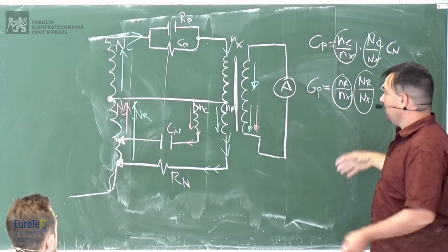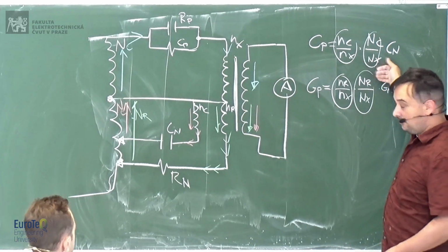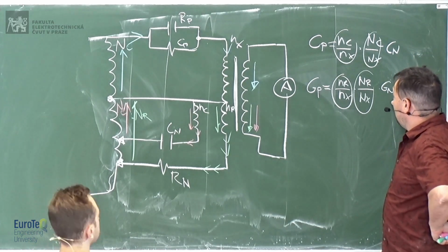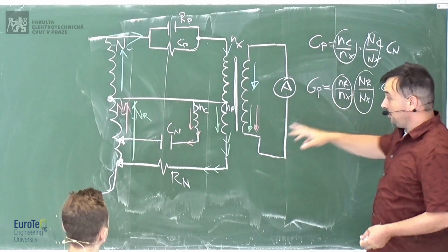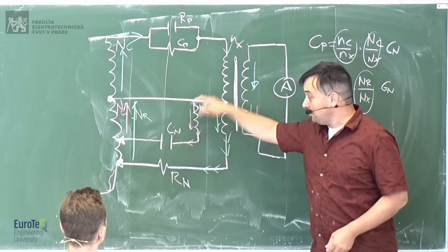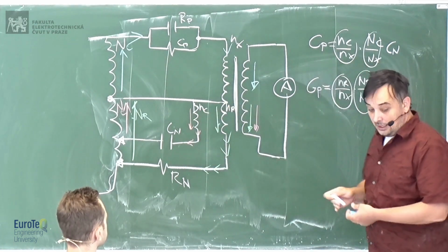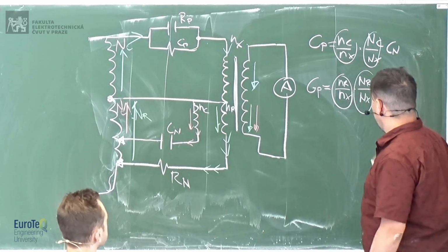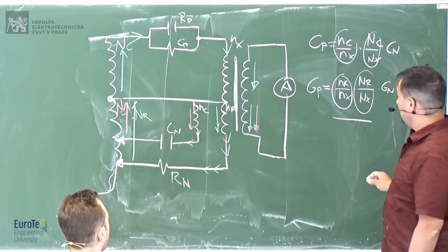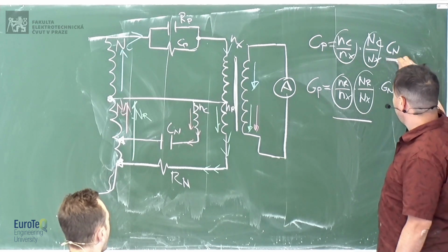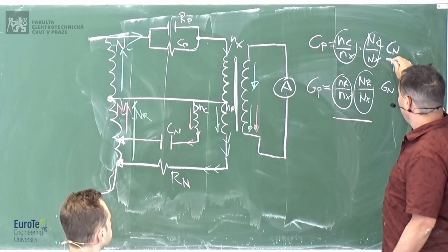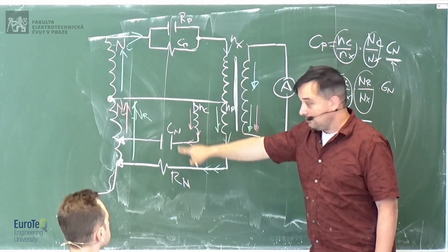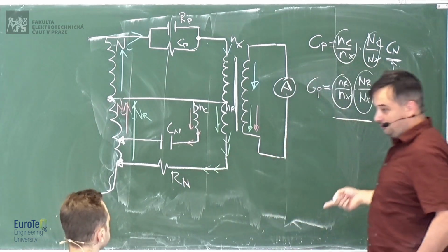Then you make your equation, you end up with this final equation. The impedance has become equal. So in this case, we don't change C and R anymore, but we change the current through them. What is the advantage here is that almost the only source of uncertainty is this capacitance or this resistance, depending on what you want to measure.